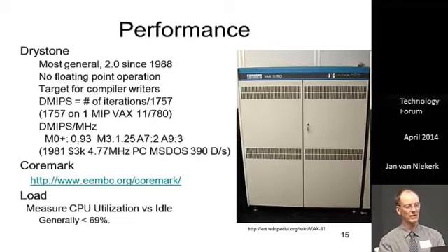It's just absolutely astounding. And just to make another point there, you can see that the M3 is slightly more efficient because the pipeline is deeper, so things are executing more in parallel. The M3 will give you 1.25 DMIPS per megahertz, and the A7 and the A9, which are state-of-the-art, extremely long pipeline, modern ARM designs, get to 3 DMIPS per megahertz.